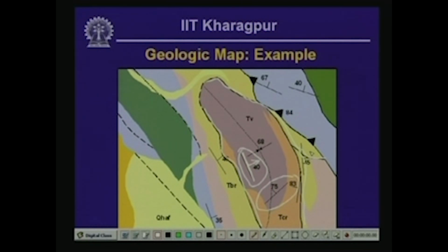So, solid thick lines indicate strikes of faults, whereas dashed lines like these are indicative of inferred fault location about which the geologist who prepared this map is quite sure, whereas lines like these, thick dotted lines, indicate faults about which there is no firm information, but these are actually inferred from the orientation of this fault at locations nearby to this area.